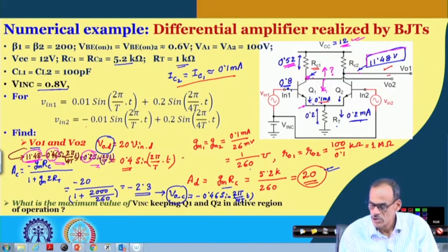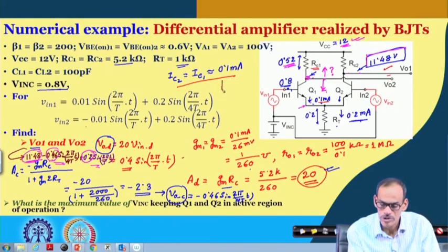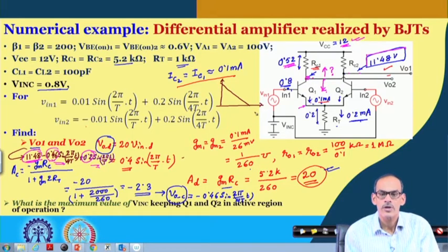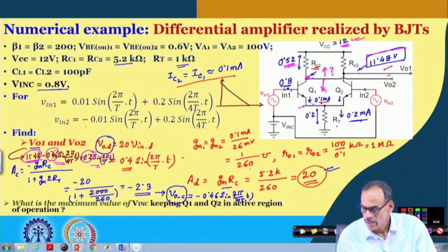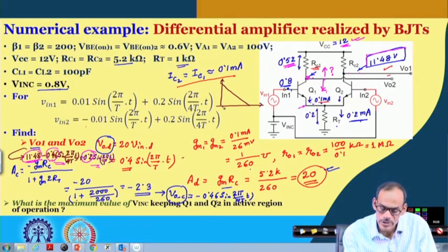In fact, you may recall positioning the operating point with respect to the load line. So, suppose this is the load line defined by the corresponding RC that we have discussed for the common emitter amplifier, and if the circuit is in good condition, then the pull down element should be such that the operating point is in the middle of this range.